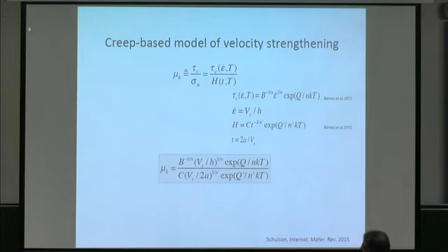So we say, well, let's imagine here, and let's define the coefficient of kinetic friction solely in terms of the critical shear stress to break away from an asperity, divided by the normal stress pushing it all together. And the critical shear stress we know is a function of temperature and a function of the strain rate that the asperity is seeing. We know as well that the normal stress, and I'm going to equate normal stress here to the hardness that an asperity exhibits. Now the hardness of ice is a function of the time for which ice is pushed against itself. The greater the time, the lower the hardness, the greater the contact area. It's a function as well of temperature.